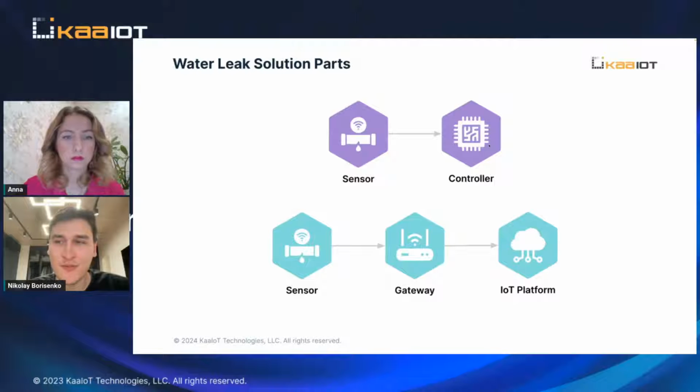Usually with this concept, all logic regarding notification, checking alerts, and availability of sensors is pointed to this controller. Sensors in this architecture are usually wired, and this approach can be used in apartments where you have the ability to do wiring.